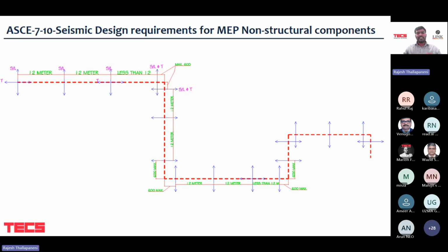And one more we discussed is end of service, where we have 1.8. So this is your service end. From the service end, the maximum we can go is 1.8 meters, where we can leave the support as a pre-cantilever where you can keep a sprinkler. The provision will be given to the sprinkler especially. So this is the maximum length that can be allowed. Beyond this, we should not allow the pipe without a seismic brace. So these are the basic principles that need to be followed according to NFPA when we are discussing fire.